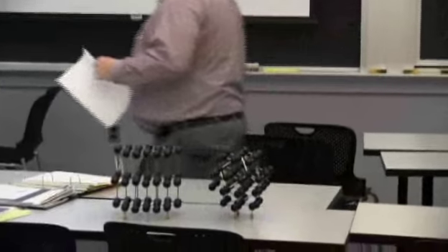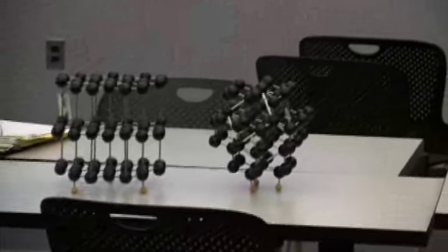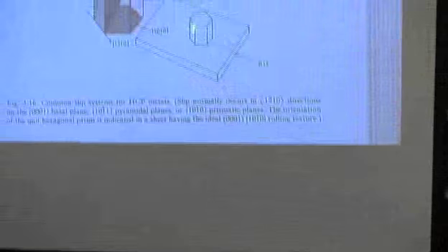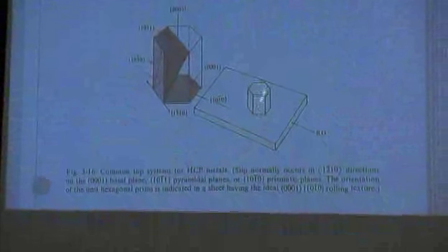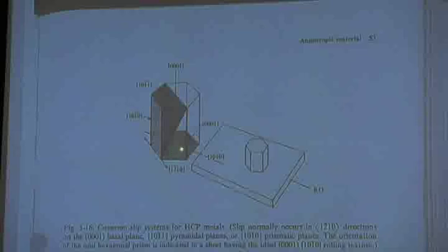And the hexagonal crystals can deform on 3 different planes. So here's your sheet, and this would be a pure basal texture. So you have these little hexagons making up the sheet. You can deform on the basal, you can twin on the, twinning is basically a mirror image of the crystal.